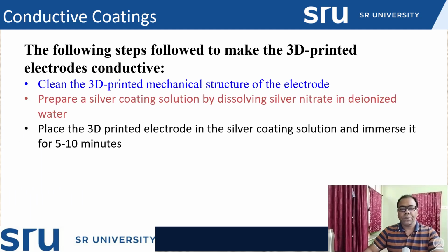After that, prepare the silver coating. For that you have to prepare a silver solution by dissolving silver nitrate in deionized water.